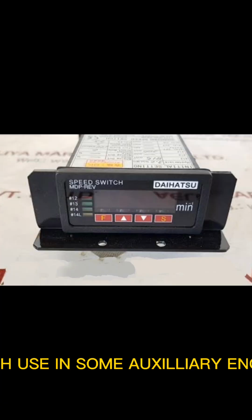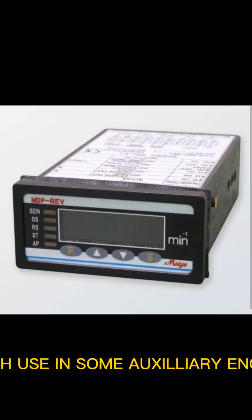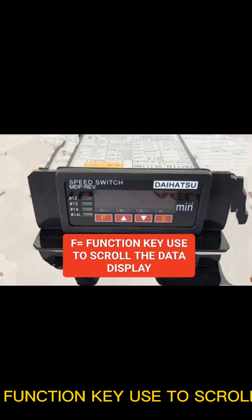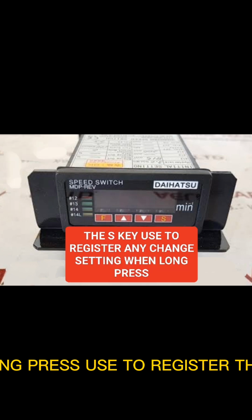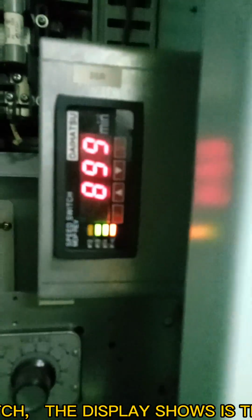This is a speed switch used in some auxiliary engines. I usually see this in Daihatsu engines. Let's familiarize. The F is a function key used to scroll the display you need to view. The arrow up and arrow down are used to increase and decrease the data or setting you change. The S key, when long pressed, is used to register the data you've changed. Now let's test using this speed switch.